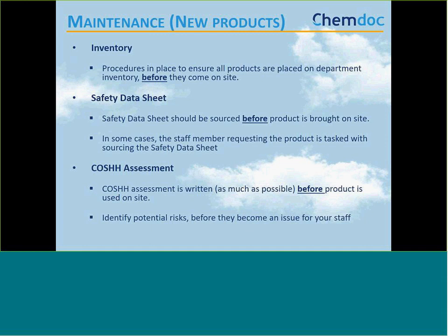It's not always possible to write a full COSHH assessment for a chemical before it's on site, because very often when you bring it on site, it may be used differently from the previous chemical, you may have to follow instructions, and the process may not be fully ironed out until you have the chemical. But at the very least, you should assess the risks and look at what the hazards are and ask, am I introducing any new hazards here that my staff don't know about and that I don't have appropriate PPE or controls, etc. for? So just have one process in place.